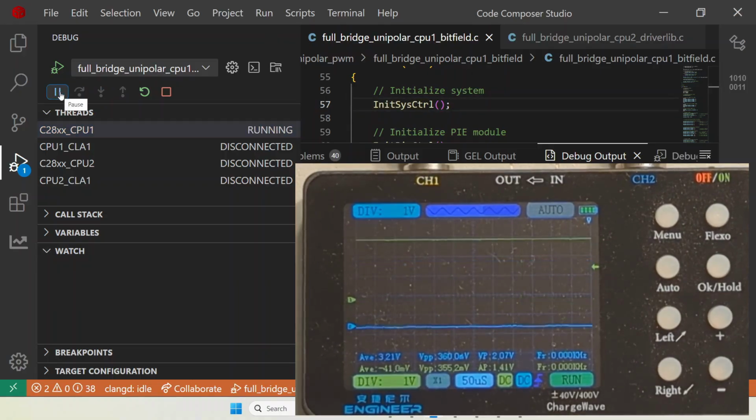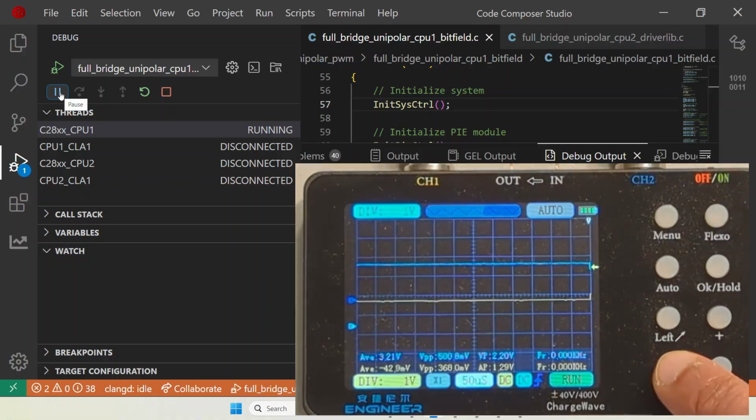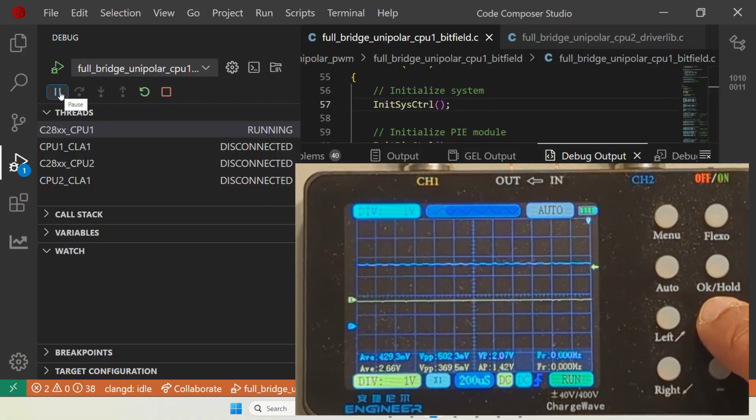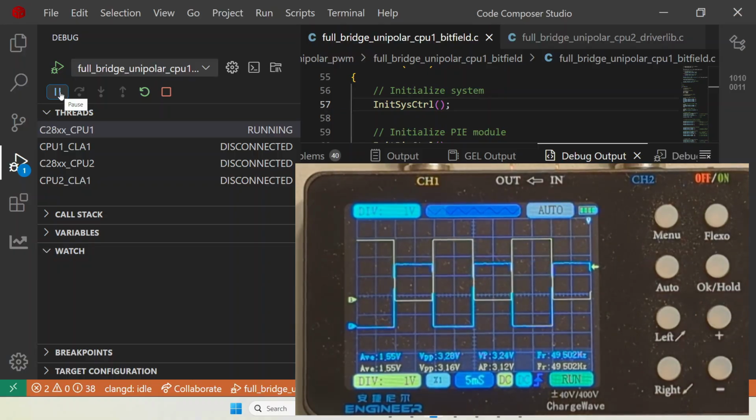You will now see a very interesting waveform, and the reason for this is that we have the same time setting as we did for observing the 5 kilohertz and 10 kilohertz waveforms. We now have a 50 hertz waveform. So I'm going to come here and change the time setting. I'm going to increase it. So now we are at a 5 millisecond time period, which means each rectangular waveform has an on time and an off time of 10 milliseconds.